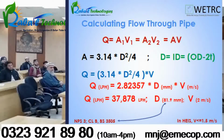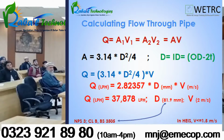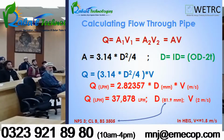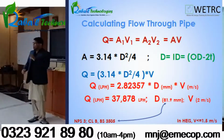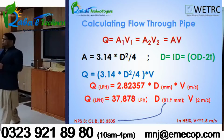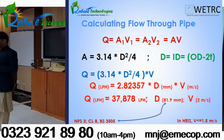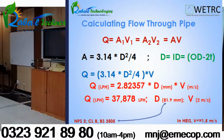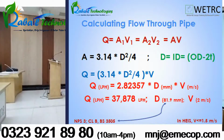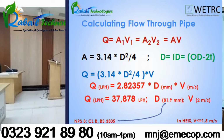And what about the Pakistani standard for pressurized pipes? Let me be very frank, it's the exact copy of the British standard, and it's called PS5051 if I'm not mistaken. In that standard, whatever product you buy from the market as an engineer, it must meet the standard of BS3505 if it is manufactured to that standard. Even in Pakistan, to a very low extent, we use the DIN standard, in PVC I'm talking about, or ISO standard. But I would say that 99.9% of the market availability is BS3505.